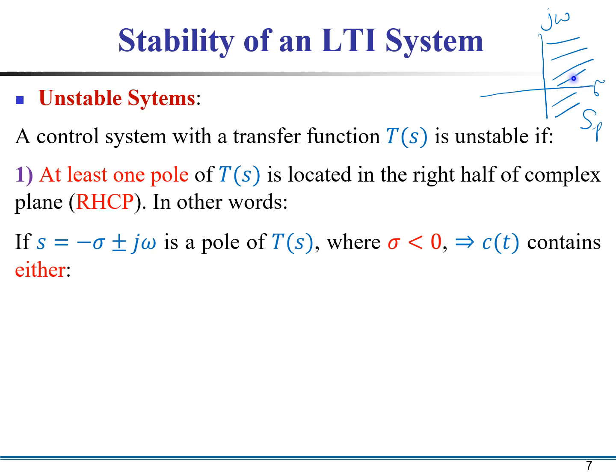If there are many poles, and most of them are in the left half s plane, a single pole in the right half is sufficient to say that the system is unstable. So for an unstable system, there can be one or more than one pole in the right half s plane.